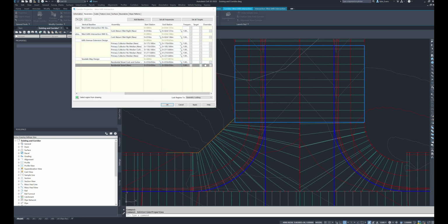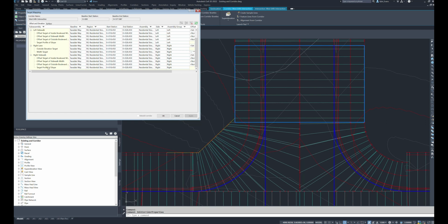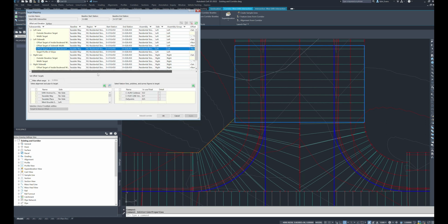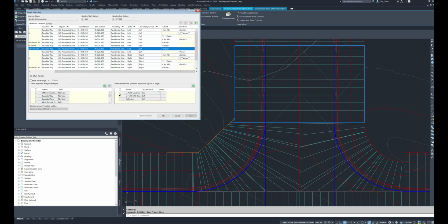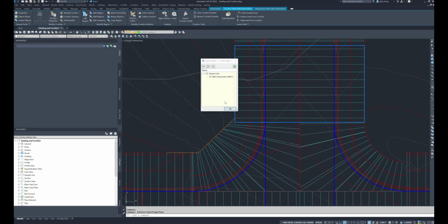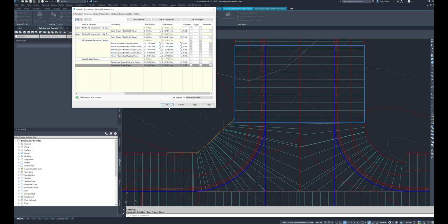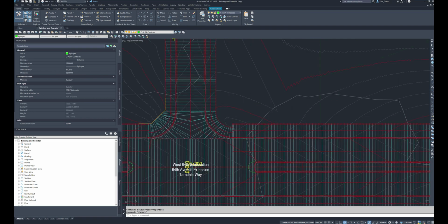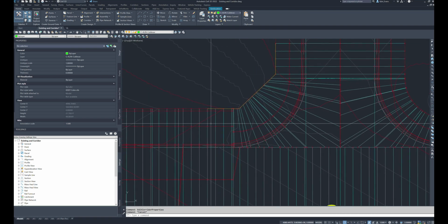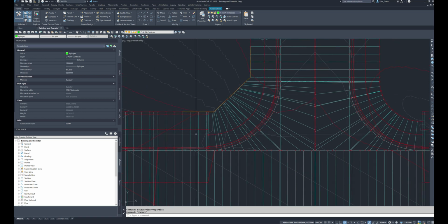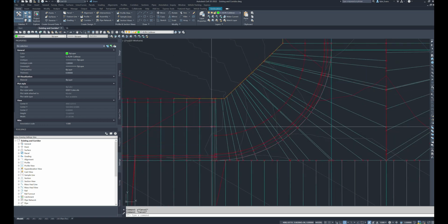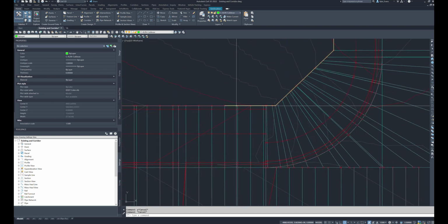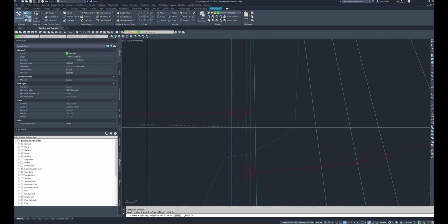And if we wanted to modify our targets, it will be the left sidewalk, sorry, outside boulevard width. We can do a C feature line. We can choose our west intersection. Hit OK, hit OK, and rebuild, and it should bump that section out for us. Now I'm going to try and do the same thing with my sidewalks. So I'm again going to draw a polyline or a 3D polyline, because I'm snapping to the corridor is why we have to use a 3D polyline.